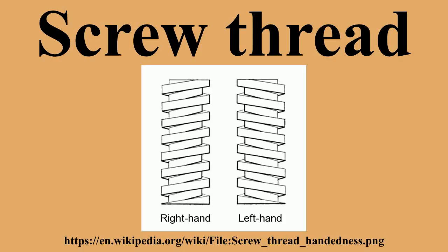Classes of fit. The way in which male and female fit together, including play and friction, is classified in thread standards. Achieving a certain class of fit requires the ability to work within tolerance ranges for dimension and surface finish. Defining and achieving classes of fit are important for interchangeability. Classes include 1, 2, 3, A and B, and various systems such as H and D limits. Tolerance class is thread limit.